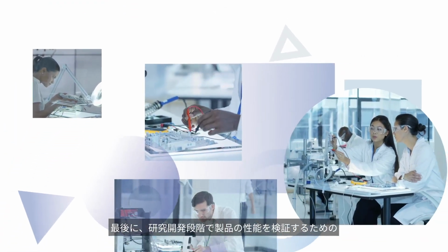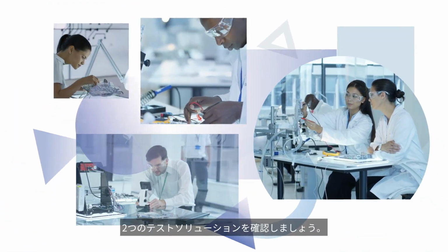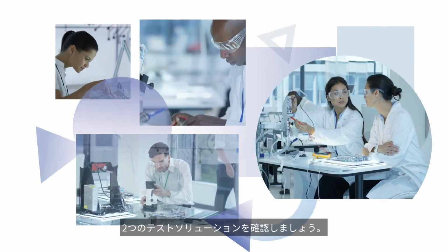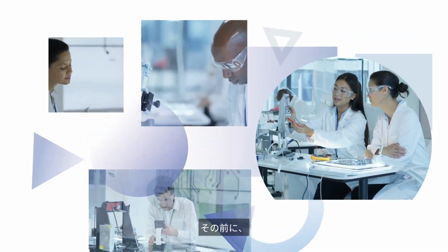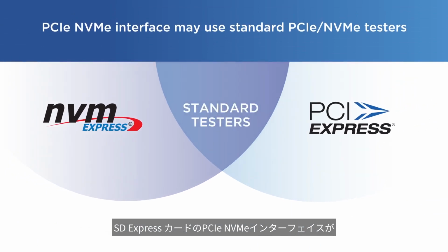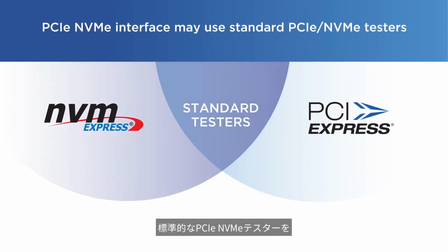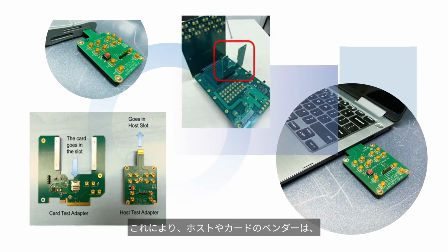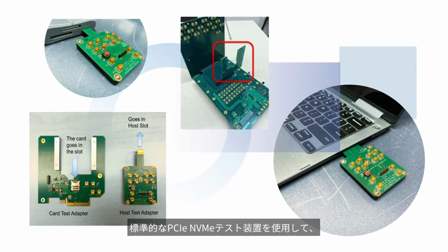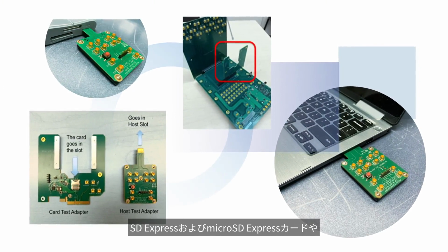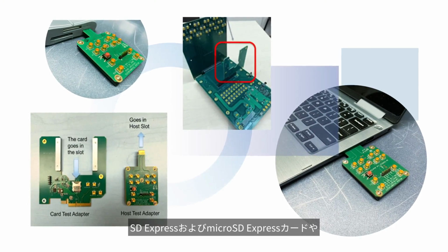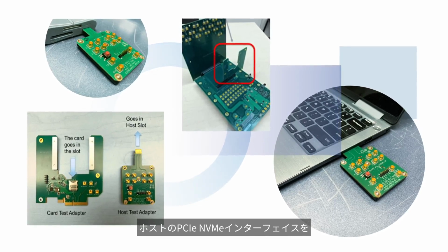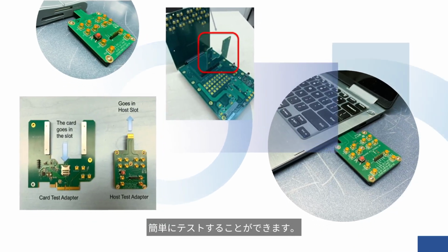We would recommend contacting the various connector vendors to understand the level of support currently available. Finally, let's review 2 testing solutions to verify your product's performance during your research and development phase. But before we do that, it's worth noting the PCIe NVMe interface of the SD Express cards may use standard PCIe NVMe testers. The SDA lets members borrow test fixtures. This allows host and card vendors to easily test the PCIe NVMe interface of SD Express and microSD Express cards or hosts using standard PCIe NVMe test equipment.